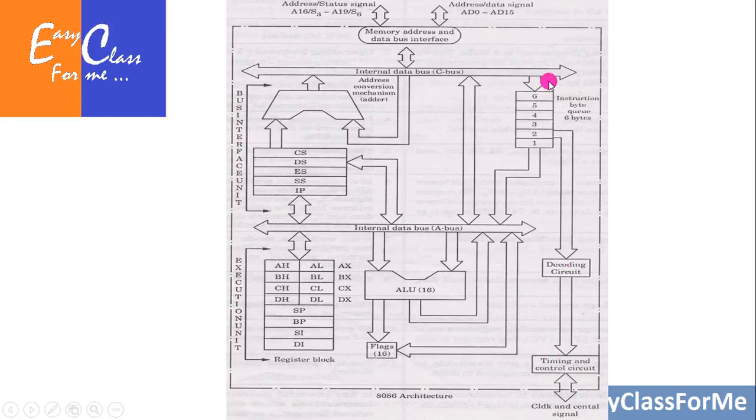So this is how a microprocessor looks from inside, and we saw the structure of externally interfaced memory also, where we said that the externally interfaced memory is 1 megabyte and it is further divided into 4 segments of 64 kilobytes each, and those 4 segments performed independent operations of storing code, data, extra segment and stack segment. So these are the registers which hold the first address of that. So a lot of more things were discussed in that lecture, so before going to the current lecture you should see that also because that will be useful.